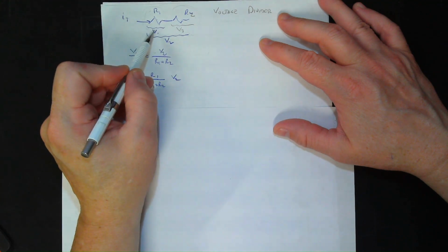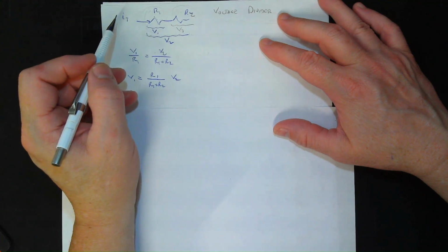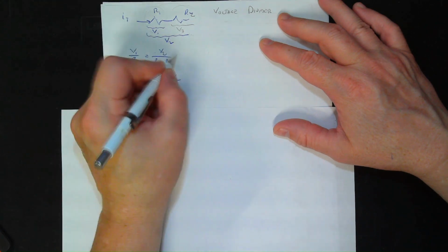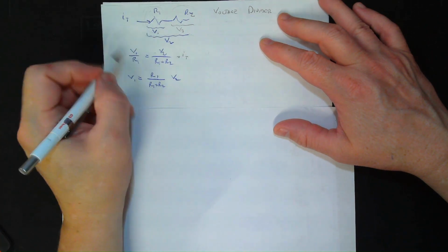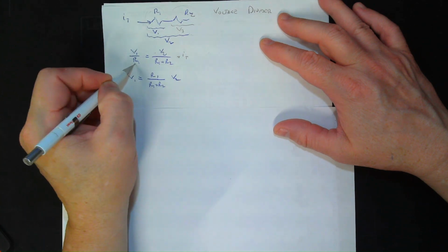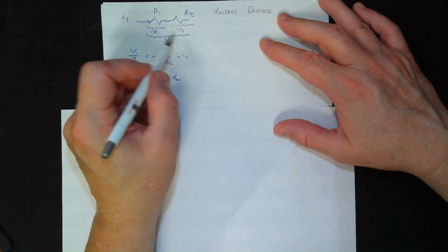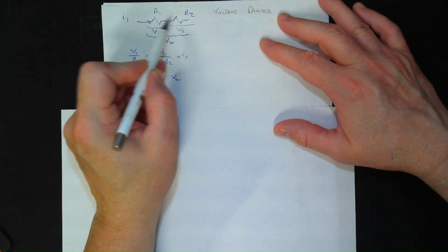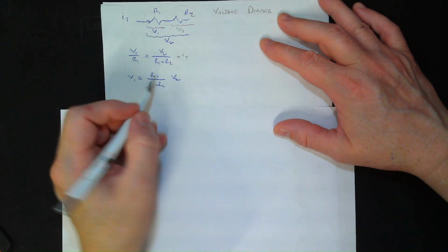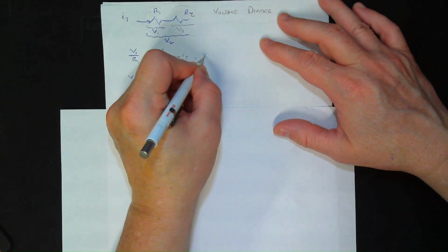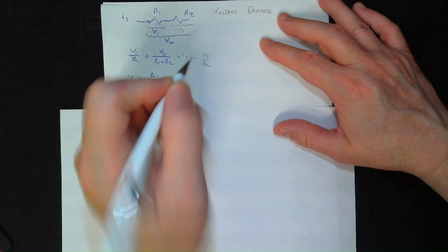Voltage divided by resistance is current. So I can just write it out here. Voltage 1 divided by R1 will be the current. For the combination, voltage 2 divided by these two added up, resistors in series. And I'll note that I can do V3 over R2.